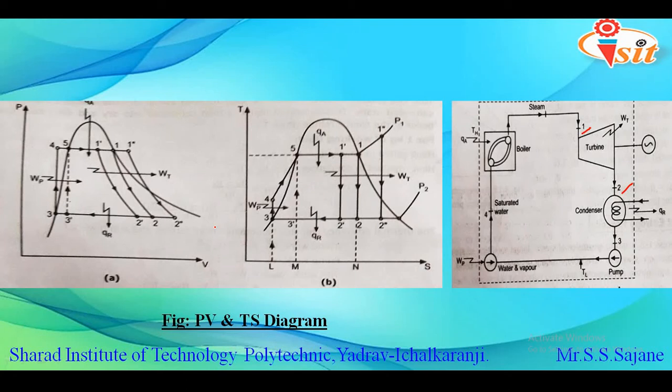After this condenser process, the next process is indicated by 3 to 4. In the steam power plant diagram, between 3 and 4 we have the feed pump. The main function of the feed pump is to increase the pressure, or to transfer the condensate from the condenser back to the boiler.